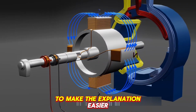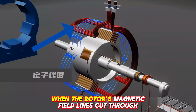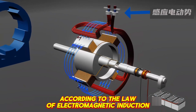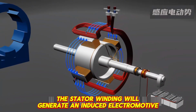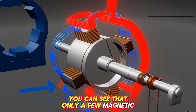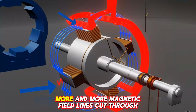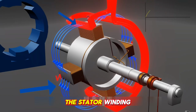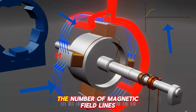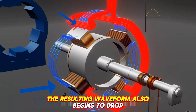To make the explanation easier, we will now take one set of the stator coils to look at individually. When the rotor's magnetic field lines cut through the stator winding, according to the law of electromagnetic induction, the stator winding will generate an induced electromotive force. When the rotor's end pole is in this position, you can see that only a few magnetic field lines are cutting through the stator winding, but as the rotor turns, more and more magnetic field lines cut through the stator winding. The resulting waveform is as shown in the figure. As the rotor continues to turn, the number of magnetic field lines cutting the stator winding decreases again. The resulting waveform also begins to drop.